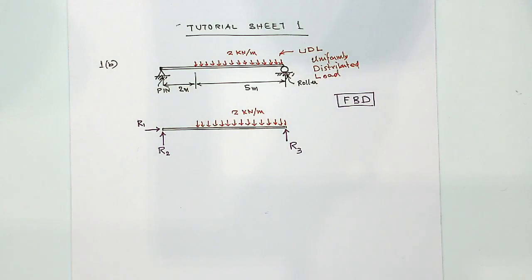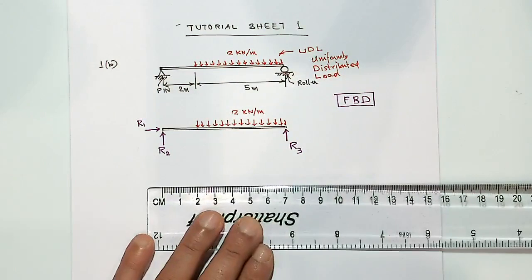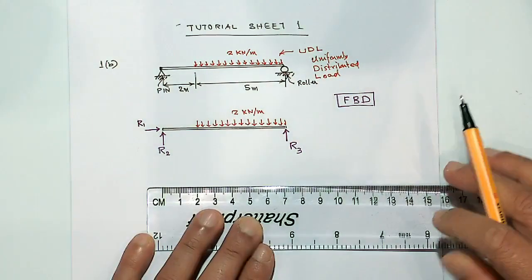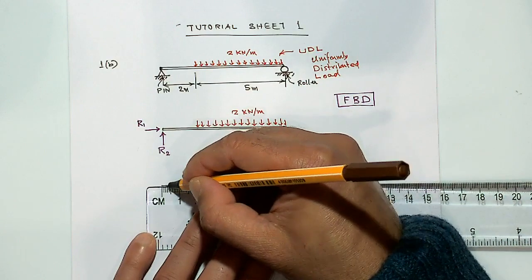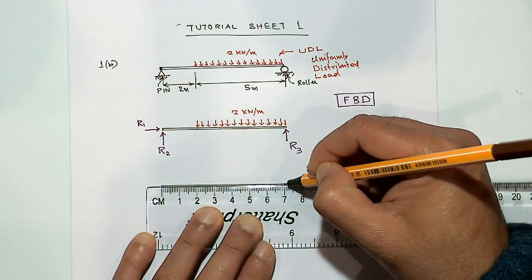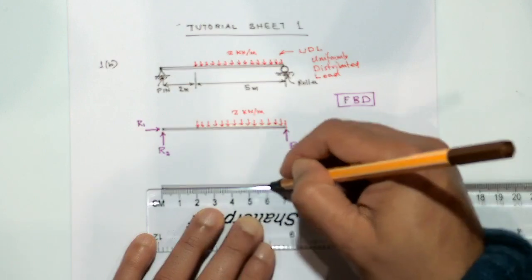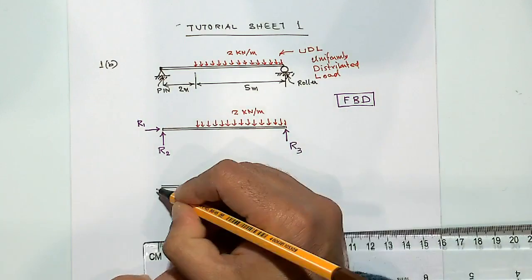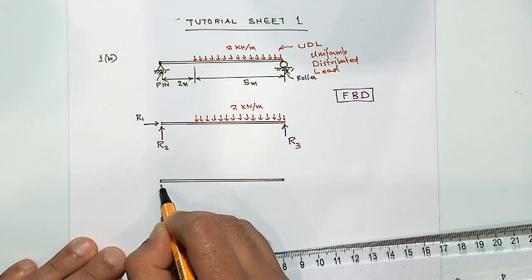So often it is useful to sum it up, and for this type of problem, when you are just calculating the reaction forces, it is better to consider its net effect. Net effect means you sum up the total forces and put it at its action point.